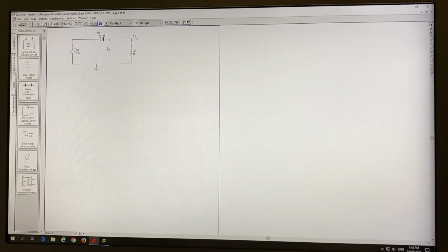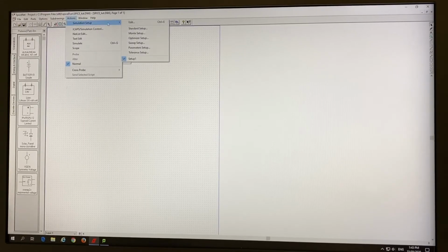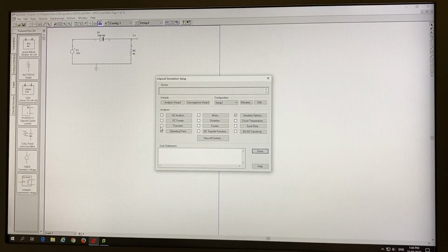Then on this diode analysis, we want to change the analysis. Initially, we did what we call an operating point analysis. Now, I want us to do a DC sweep on this diode. So remove operating point analysis. I want us to do a DC sweep. Now, once I click this, we're going to see a drop-down menu. This drop-down menu is very important.